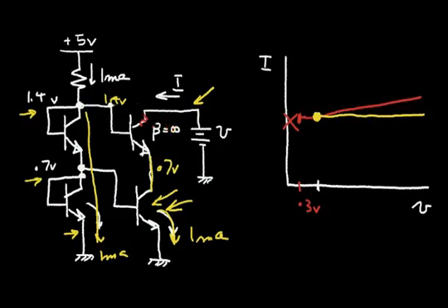So again, I have this junction diode here that I do not want to forward bias. If my base voltage is sitting at 1.4, I could go down to perhaps around 1.0 volts or so here. So this current source, let me change colors, will have an operating range here of about 1 volt. I don't want to operate it in this range. So I've lost some voltage margin on my current source, but I've gained a very constant current source. And sometimes that might be useful.